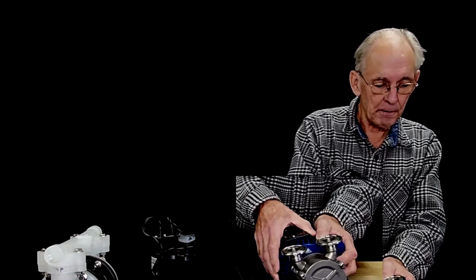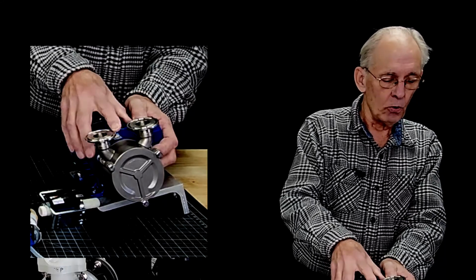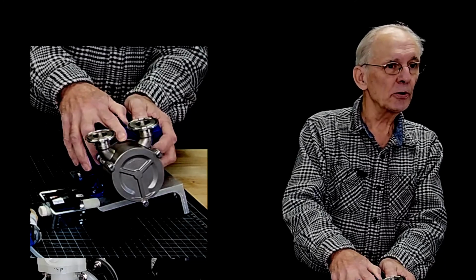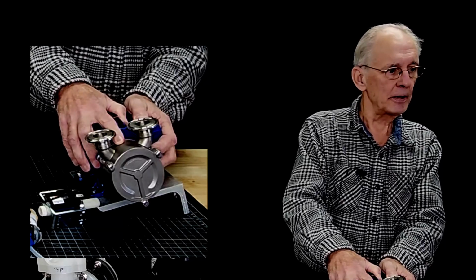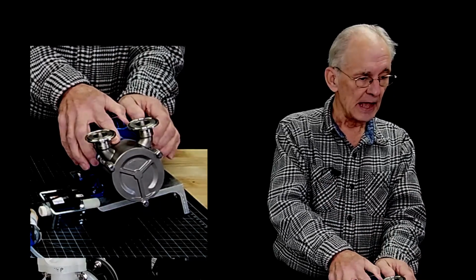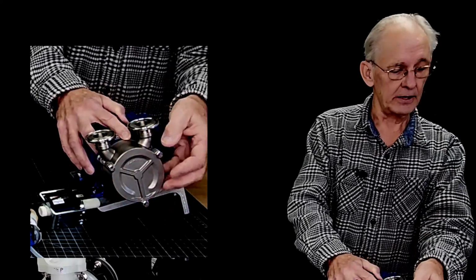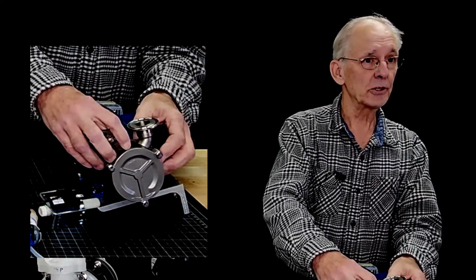This pump is semi-centrifugal. I spent 10 years looking for this pump. Why? Well, I didn't know it existed. Or I had heard of it, but I didn't know how it worked. So this pump is called a side channel pump. In a side channel pump, the water isn't directly pumped by the rotor. It's not a centrifugal pump in that it doesn't have a rotor that's kind of spiral. This has a rotor with straight blades. And the water is pumped in a channel on the side that is not actually the rotor.